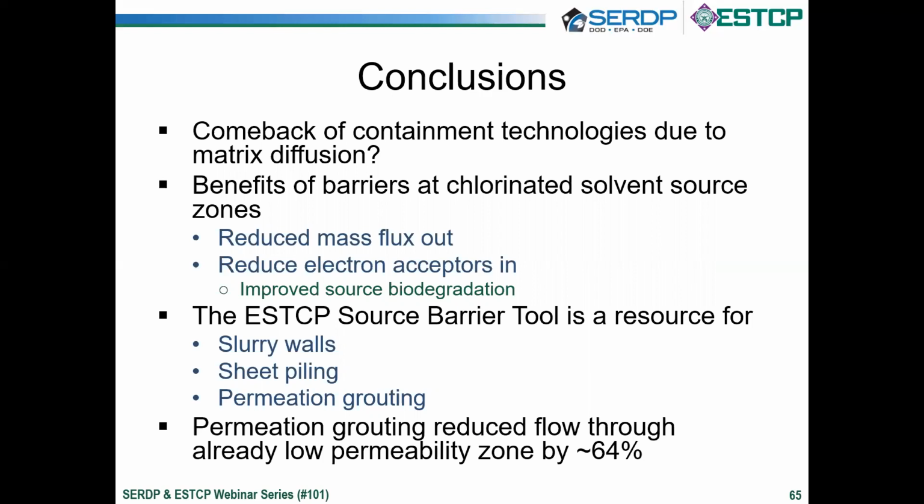Finally, in this first application of using permeation grouts with injection-based technologies, we reduced an already low permeability zone by about 64%.